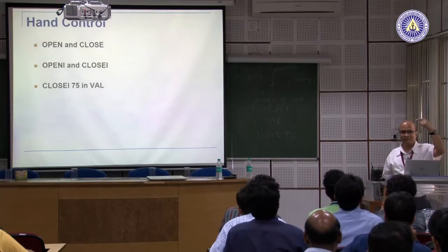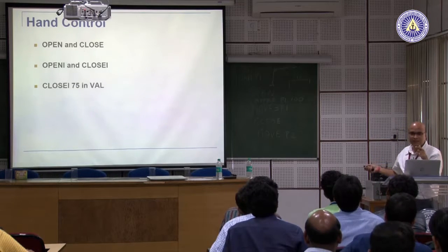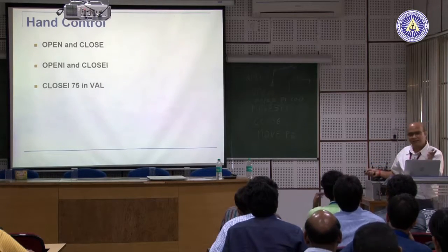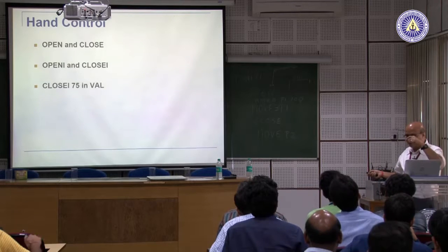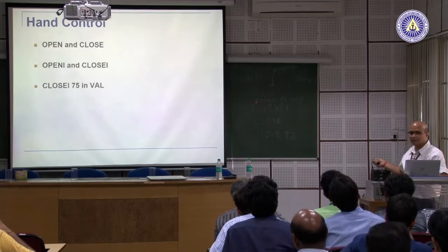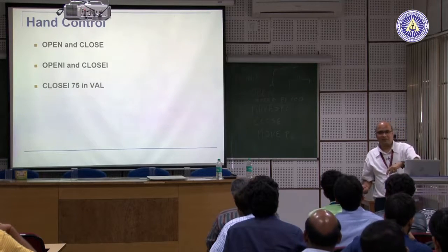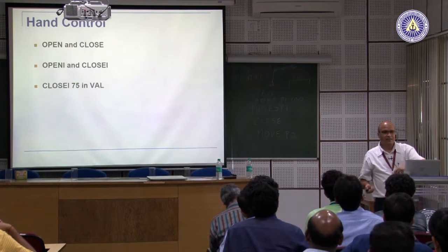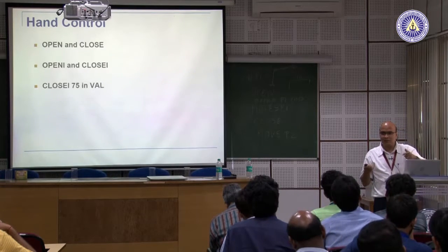Do you understand? Similarly, here the gripper is opening, as far as the program is concerned, it has given the command to open, right, but it is taking time. So, in the process of opening, it is also moving. So, if the object is very near, it will go and hit the object. Do you follow? Every line takes time, but as far as the program is concerned, time is not in the picture in a program.